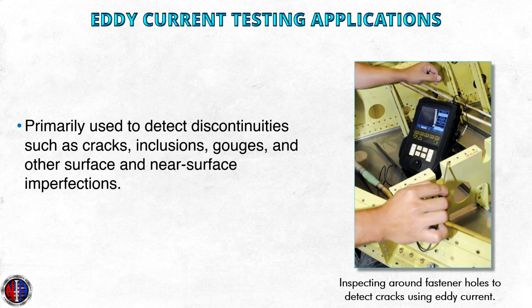Eddy current applications. Eddy current systems can be utilized beyond discontinuity detection. Eddy currents are useful in determining the state of a test specimen's material properties, including changes in conductivity and/or permeability caused by a change in the part's temperature or hardening. Additionally, eddy currents are able to detect changes in conductivity due to parts subjected to localized overheating.